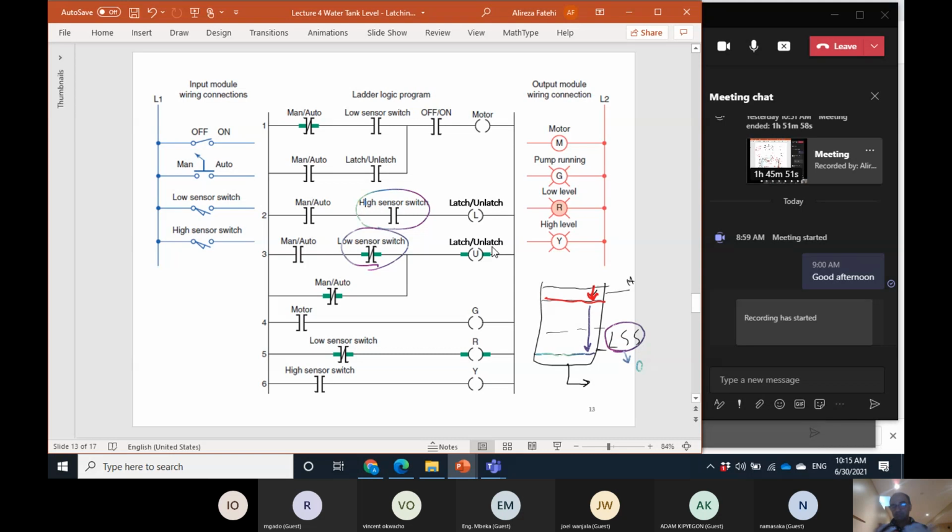So maybe in this special program, it's not that important whether we change these to rung 2 and 3, for example, or even these rung 1. Move this to here. Even if you move this to here, nothing happens. It still works. There's just maybe a very short delay on applying the command, but that short delay is in the order of, say, 100 milliseconds or something like that, if you move this to after this.